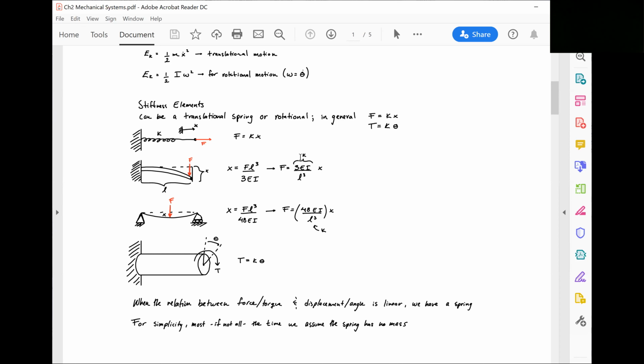By the way, this is the way that most of the electronic scales work. You have a small beam, and when you go on top of that electronic scale, this would deflect, and the deflection is measured by strain gauge, but it is the same principle. That strain, or displacement, depends on the force, which is your weight.